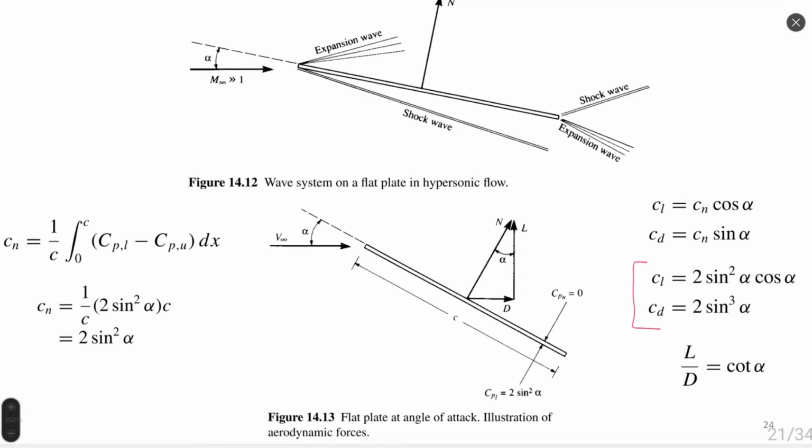Just integrating. The advantage of this model is noticeable: lift and drag coefficients could be directly obtained from these formulas. Right, when we use the approach presented on figure 12, where we have an expansion wave and shock wave, the equation system is more complex. You remember, right? We must calculate the expansion wave, the pressure on the expansion wave, this transition. Okay, this pressure here, then we need to calculate the shock wave.